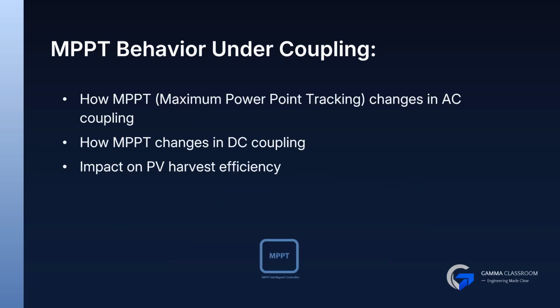MPPT behavior changes significantly depending on coupling architecture. In an AC coupled system, the PV inverter performs MPPT independently, and the PCS manages battery charging on the AC side.